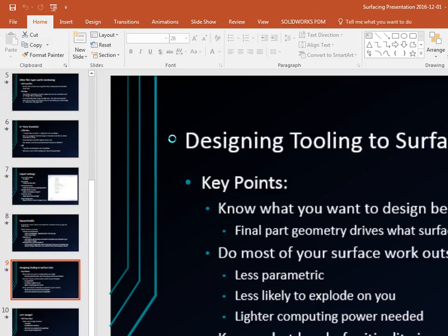So I'm going to select tangent propagation, which is really only important when you're doing variable radius. I want to set all of these unassigned points. There's a ton of unassigned points because there's a lot of little edges in there. I'm going to set them all, and boom, now it'll solve.